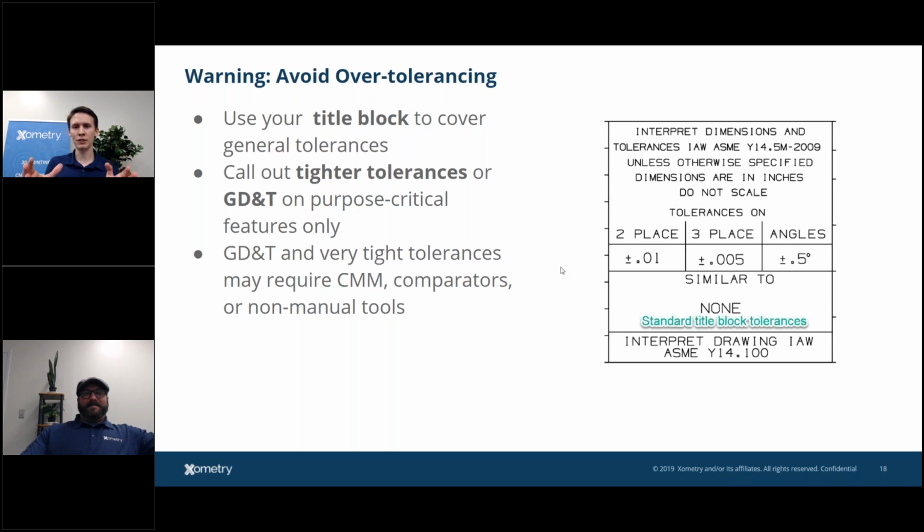If drawings inherently have confusion, like a deviation on a title block that wouldn't typically be there, or confusing units, a shorthand, a red line that may not be easily interpreted, all that stuff can really matter when it comes to manufacturing, especially production manufacturing or manufacturing where you're building multiple parts that are to be assembled.